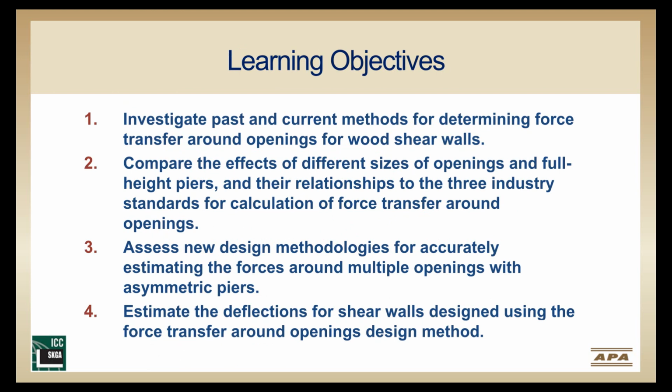Let's start with our learning objectives. We'll begin by investigating the past and current methods for determining force transfer around openings using wood shear walls. For rational analysis, there's a variety of methodologies available that engineers use regularly. We'll also look at the effects of different size openings and full height piers, the different code allowable height to width ratios, different sizes of openings, and how that impacts the force transfer and the performance of the walls. Focus on the new design methodologies to accurately design multiple openings with asymmetric piers.